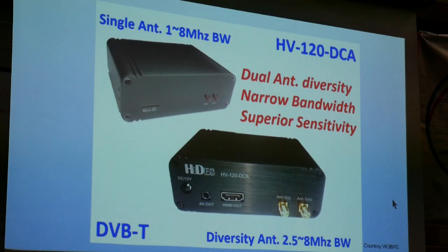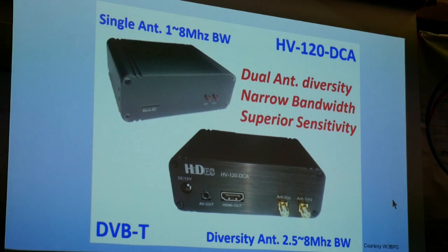Yes, you're right. He's one of our members. He's got a commercial drone pilot's licence. I've worn the second set of goggles while he's flying through the trees and things, and you can really see how the lag would kill you. So typically, I suppose people would be recording it in HD on the drone to get the full quality and sending it analog TV, because if it breaks up, you lose a few lines, but you don't lose the whole picture. Yeah, that is the disadvantage with digital. It's all or nothing.